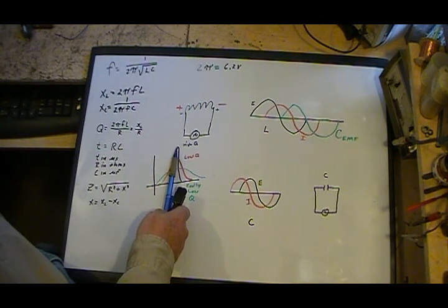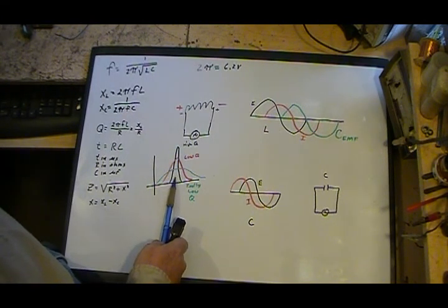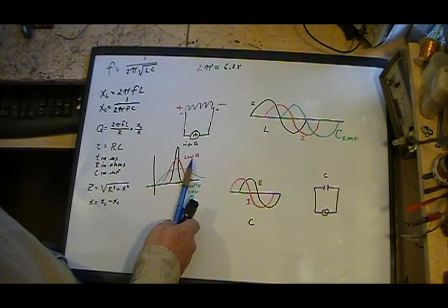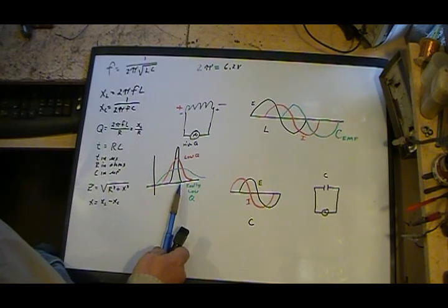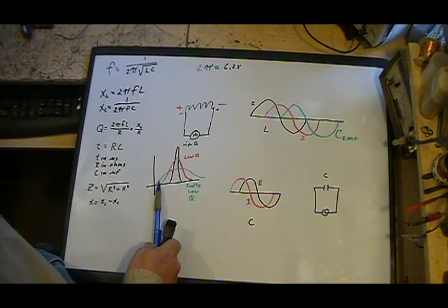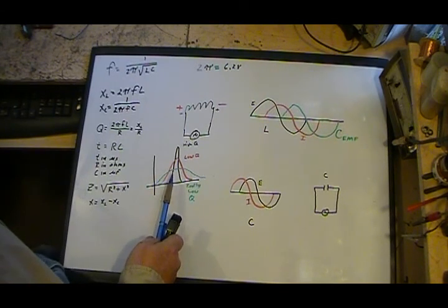When you've got a really decent high Q, you have a real selective circuit. It's very narrow band, and you get a lot of signal through it. When the Q is a little lower, it starts broadening out, and really low Q gives you an extremely broad band.